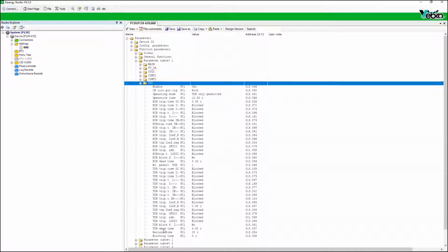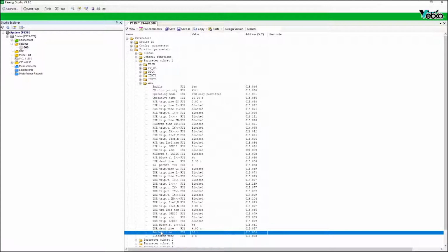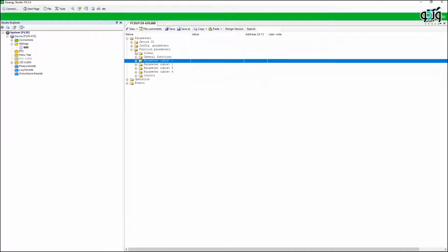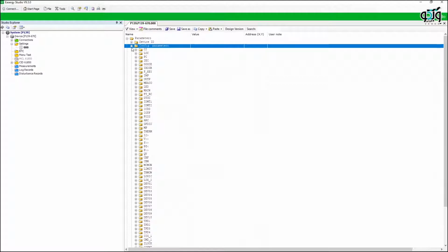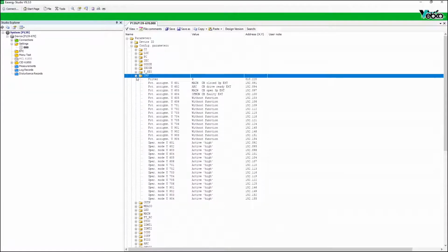Here, the TDR option refers to recloser with time delay. Dead time and reclaim time are set at 4 and 20 seconds respectively, but it is also possible to activate the HSR, which is the highest speed recloser. Next, the outputs are configured. Moreover, in the INP section, the inputs needed for the assessment and the test are configured.